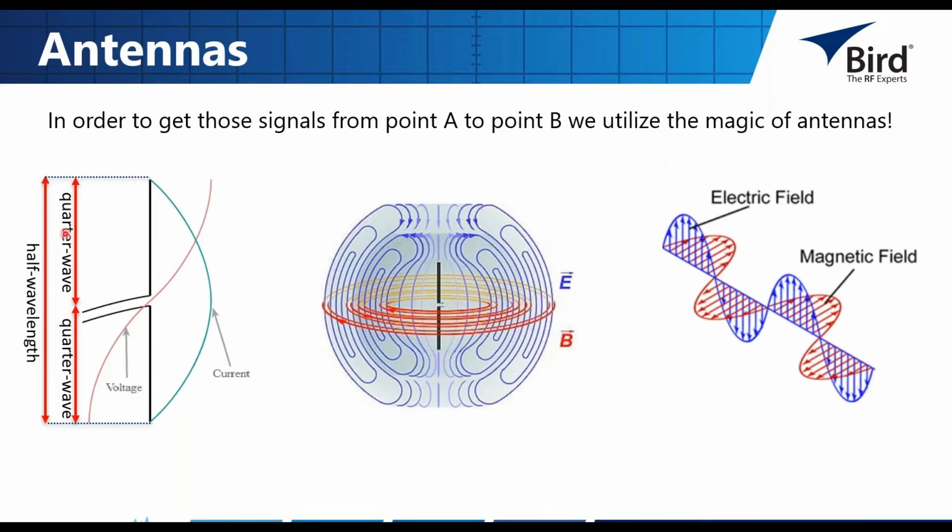Here we have an example of a half wave dipole, and we're observing that half wavelength of the frequency lining up across the body of the antenna. This is where wavelength comes up when we're talking about these EM structures. And this is going to launch an electromagnetic wave out into space, traveling with the electric field and the magnetic field perpendicular to one another.